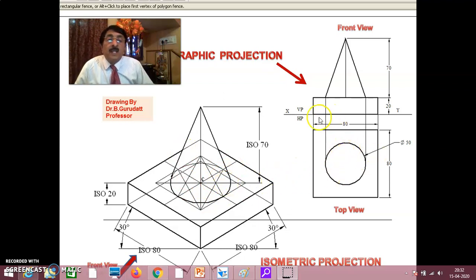Now for this, you see here, again I'll tell you, first you draw, when you're looking from here, 80-20 you draw actual, okay? Don't take any scale in orthographic projection, okay? It is just actual things. 80-20 you draw, immediately draw the corresponding 80 square, okay? That is the bottom solid, front view over, top view over.